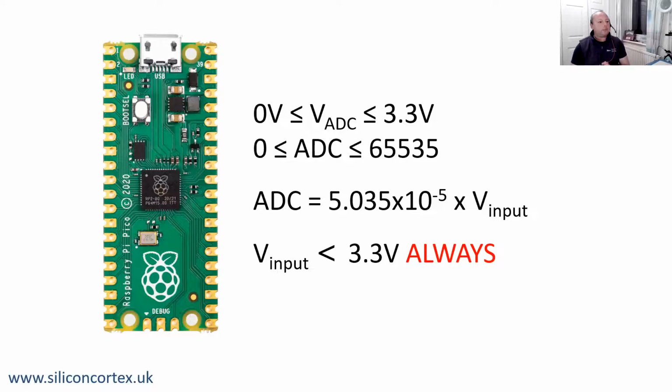Here's another view. This is a first gotcha, something I've discovered in the last couple of weeks with the Raspberry Pi Pico, so make a note of this. Under no circumstances must you ever allow an input voltage, whether it be the ADC or a logic input, to be greater than the supply rail. I had some troubles. I was using a GSM module. For some reason, the designers decided that the operating voltage for the GSM module would be 3.4 volts, not 3.3 or anything smaller.